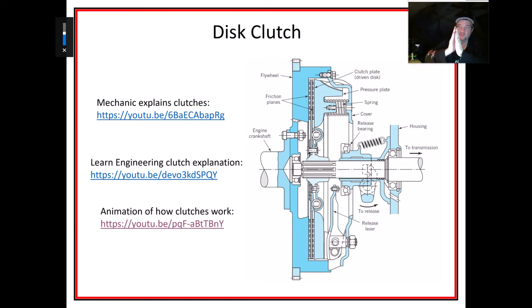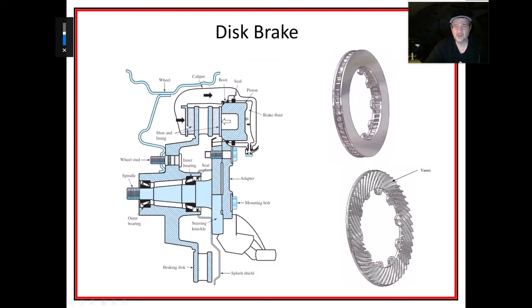And actually, what the clutch does is lift the pressure plates apart and allow them to spin independently of each other. So then you could change gears, or you could just stop, like at a stoplight or whatever, and then engage the thing when you let go of the clutch, and the two things will be joined to each other. But it's a very interesting thing, and I wasted time by showing a video inside a video in the previous recording I tried to make.